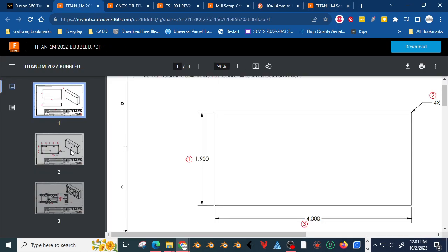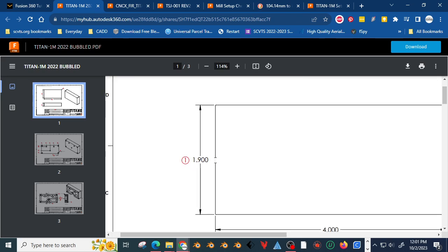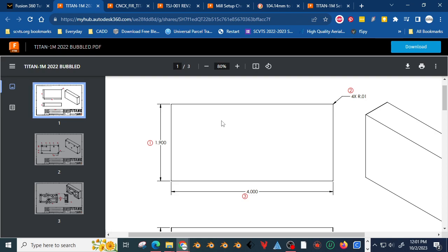All right, so if I look at the PDF, notice this doesn't say 2, this says 1.9. So what's happening is the material is actually 2 inches wide at that spot, and this material is actually 4.1. So in both directions, that has 0.1 more, and it ends up splitting that difference. So it's 0.05 on each side.